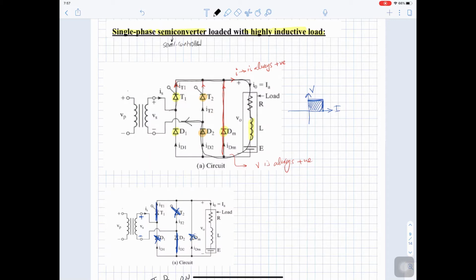Although the diode is not controlled, you have the thyristor in the path controlled, which gives you control over the whole path, because thyristor 1 and diode 2 act in series, so controlling one switch of them is sufficient. This is a smart move to reduce your cost.